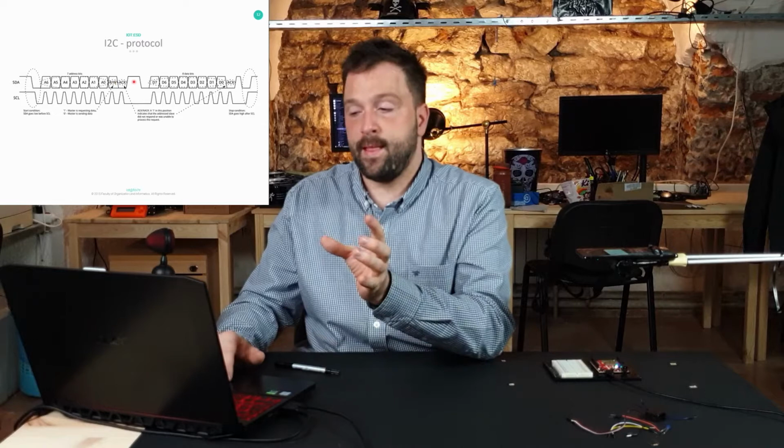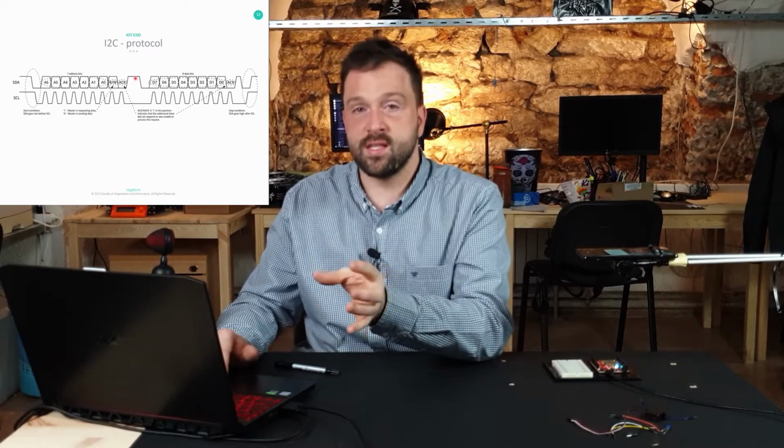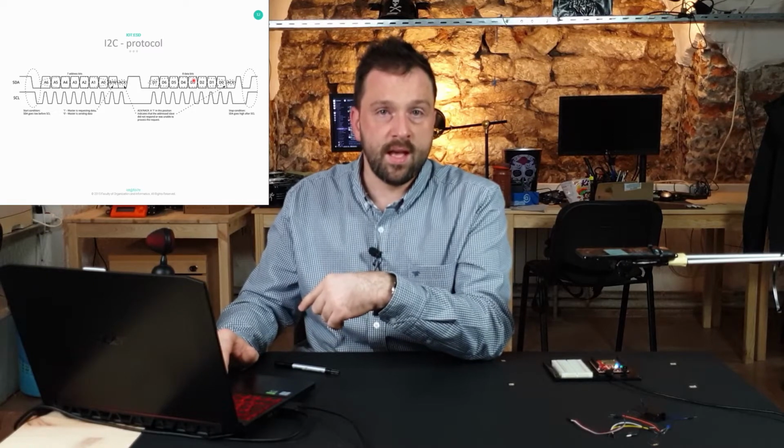And this is some acknowledge bits and so on. Let's ignore this for now. And after that you have some period of delay. During this time, the device could gather data or whatever is necessary. But if I'm sending 0 here, it means that the master is going to send the data, and all of the slaves should listen, especially the slave that's being addressed.